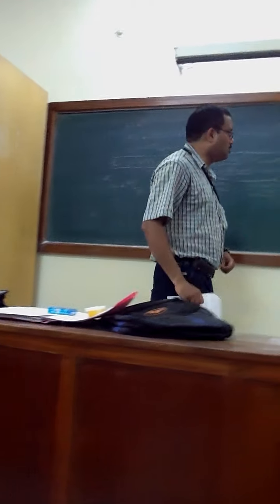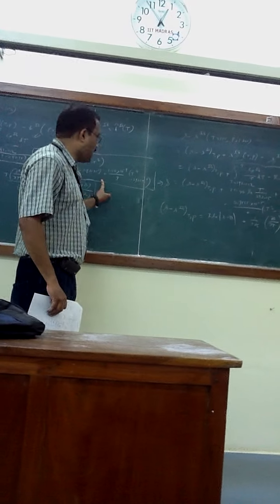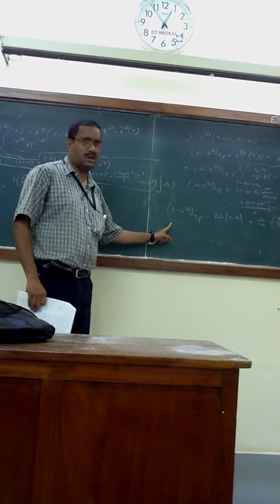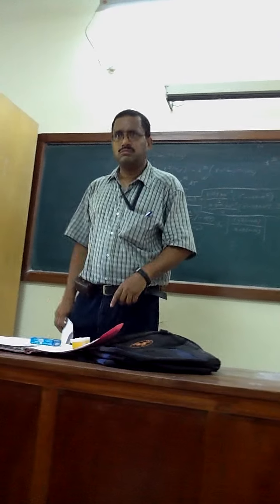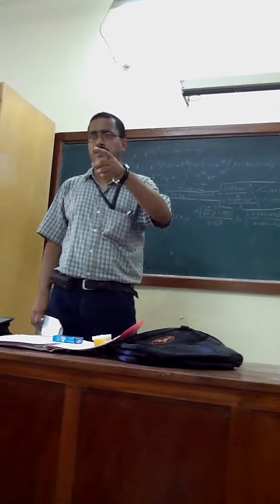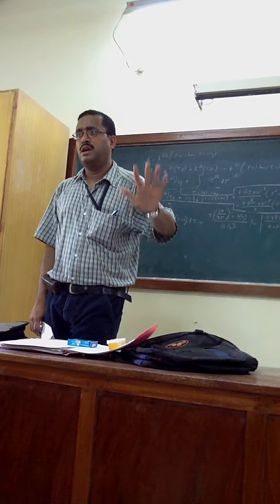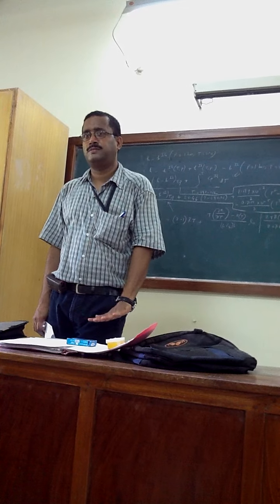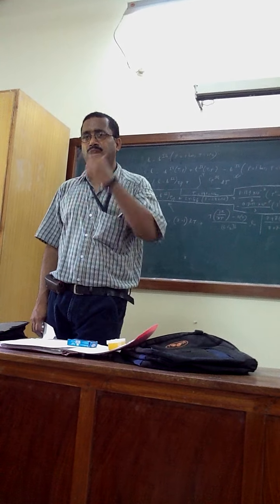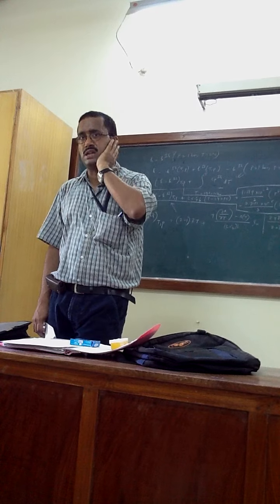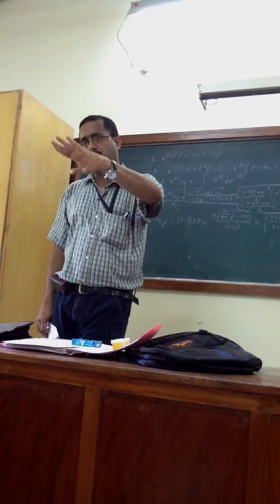So this will give you the pressure enthalpy diagram and this will give you the pressure entropy diagram. Okay, so in table A and table B, you had Z, B, H and now S. In the same table, fix T equals to minus 100 degree centigrade, fix P equals to 1 bar.